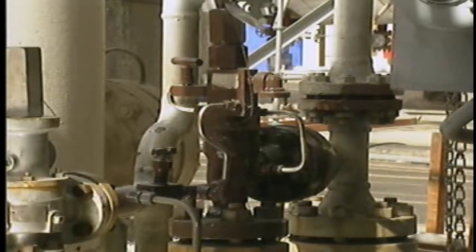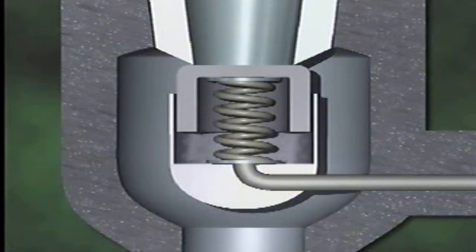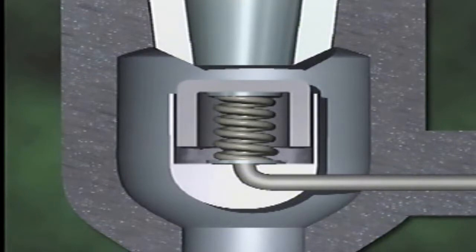Pilot-actuated relief valves, however, can be isolated from a system because they're not a primary part of the system safeguards. So, the pilot-actuated relief valves can be used and then repaired if necessary without having to shut down the system. The disc opens downward, allowing the steam to escape through the outlet at the upper part of the valve body. Also, in this example, the spring is placed below the disc. The valve also has a disc guide, which is a sleeve that aligns the disc with the seat.